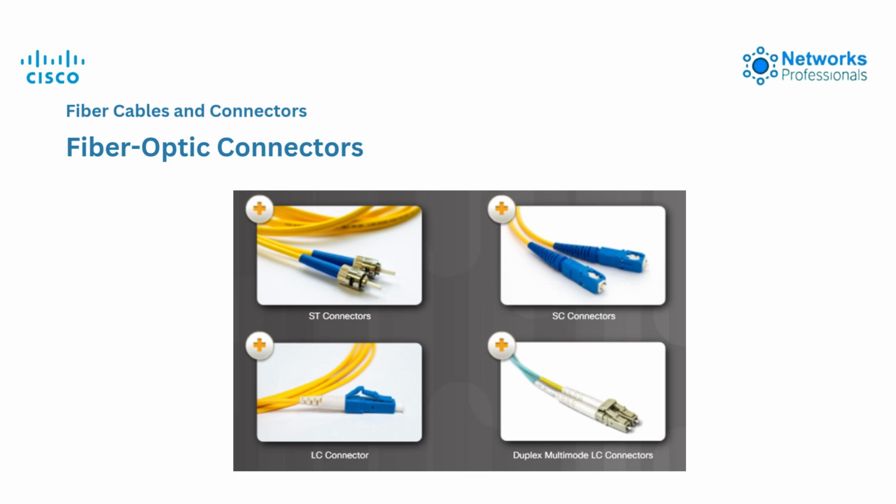Design. ST, straight-tip, connectors are one of the older types of fiber optic connectors. They feature a bayonet-style coupling mechanism, meaning they twist and lock into place. Usage. Primarily used in single-mode and multi-mode fiber installations, particularly in older networking setups. Advantages. Simple to install and use. Secure connection with a twist-lock mechanism. Common applications. Telecommunications, legacy networks, and other environments where fiber optic systems were set up years ago.